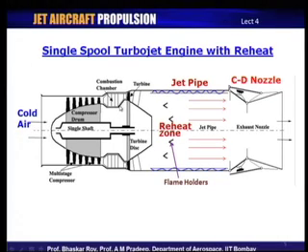We do not see them in this particular diagram, but there are certain versions of flame holder normally used in any combustion chamber. Now, here the entire exhaust or jet pipe here is used for the combustion process, and in this combustion process we have large flame holders in which the fuel is injected and the gas is again raised to high temperature.